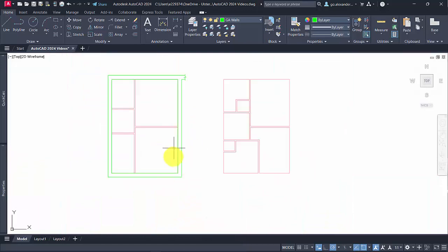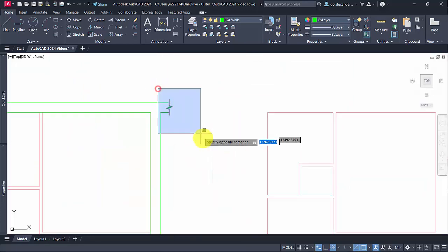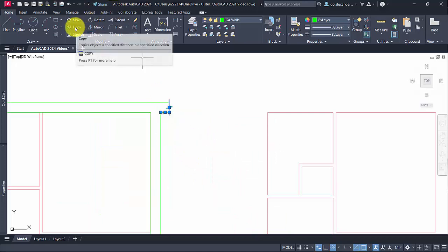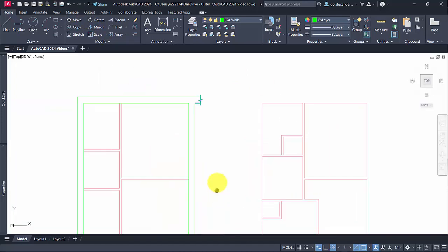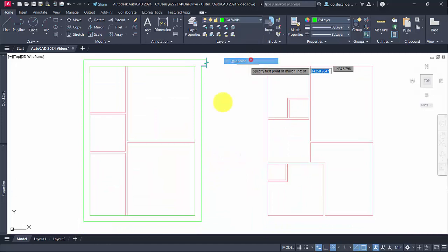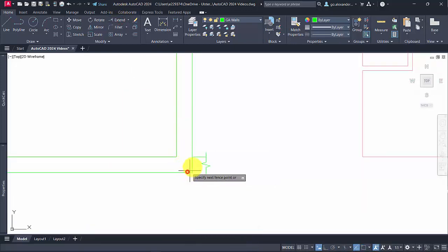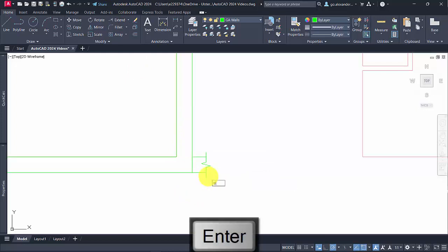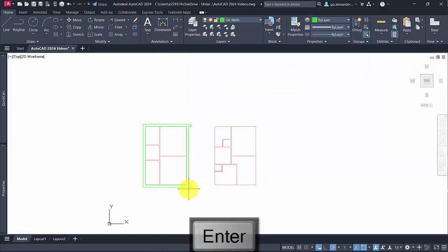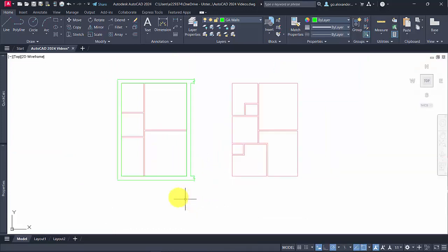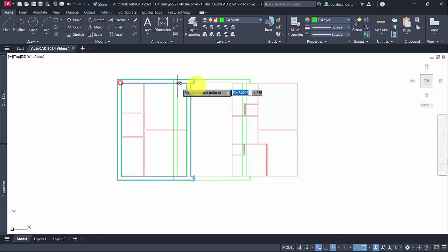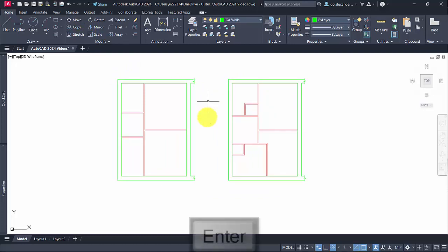What we also want then is that down at this end of the building, so we can copy this. In fact, it's probably a good idea to mirror it, and let's just make sure we get the midpoint of the internal line of the party wall as such, and then we can extend that line and trim this line. And just for completeness then, what we could do is copy over the first floor plan, or from the ground floor plan to the first floor plan.